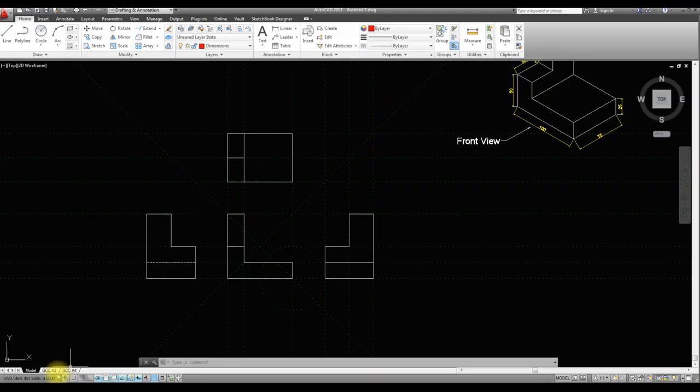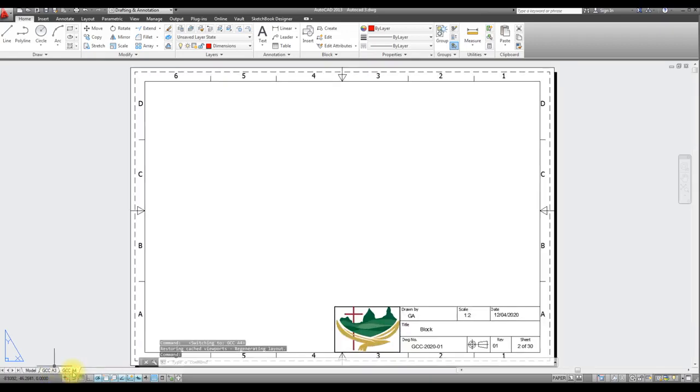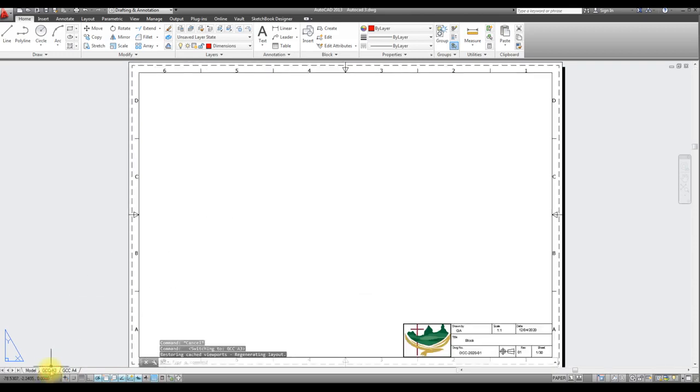That's what we're doing. We're communicating ideas and designs to people that either want to just inspect the work that we've done, or to go further to people that are going to actually fabricate the part. So this is a universal method of communication. You notice I've got an A3 layout and an A4 layout. The only difference between the two, obviously, is the size, but fundamentally, just looking at them, there's really not much difference in appearance, except the title block.